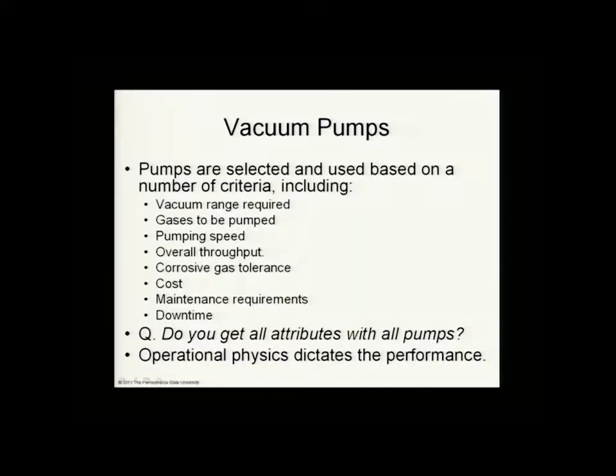And then, as we said, you have to worry about the gases you're pumping. Some can be corrosive. Of course, you have to worry about cost of the equipment, which includes not only the initial purchase price, but also the cost in maintaining the piece of equipment. And you have to ask the question, especially when you're interested in production, is the downtime that's going to come with any piece of equipment acceptable?